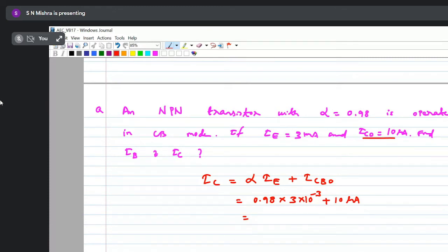The most common configuration is the forward pumping at 980 nanometer pumping, because that configuration has the advantage that the 980 nanometer semiconductor laser diode features effective cost, reliability and low power consumption.